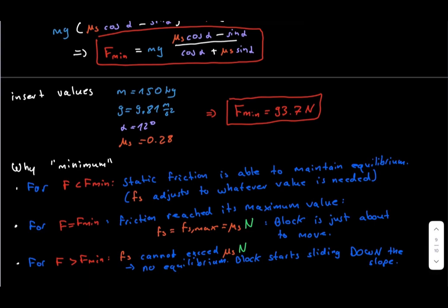First, determine the impending direction of motion. Friction always acts opposite that direction. Then choose axes parallel and perpendicular to the contact surface. Determine the normal force before calculating the friction limit. And most importantly, only use the maximum friction relationship when the object is just about to move.